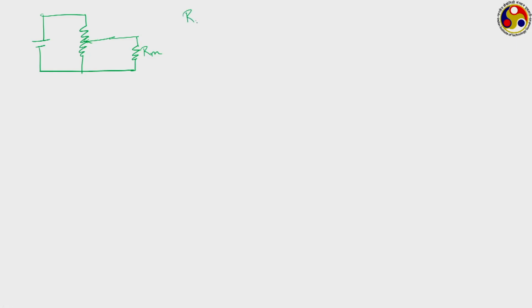The length of the resistor is xt, and this particular distance is given by xi. Say Vex is the excitation voltage and V out is the output voltage. So, we have to see how this output voltage V out is being affected by the presence of this Rm, or maybe the relation between Rp and Rm.